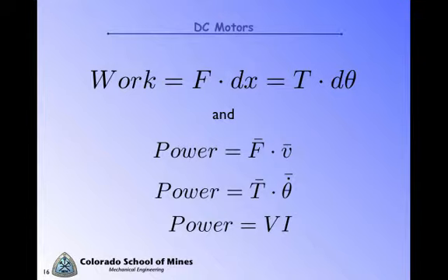And in terms of the input to the system, since it's an electrical input energy, it's volts times amps. So the efficiency, as you may have already thought to yourself, will be the torque times angular velocity divided by the voltage times amps, which is the output over input.